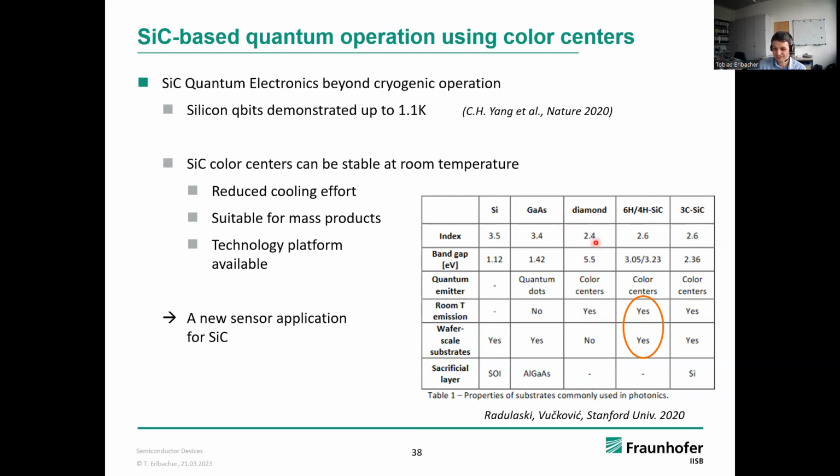So usually you have a color center in diamond, the NV center, and then you try with 19-inch rack equipment to make something out of the color center, because there is no integration of electric field or magnetic field manipulation around the color center, which we quite readily can do with pin diodes or MOSFETs that are integrated close to this color center.